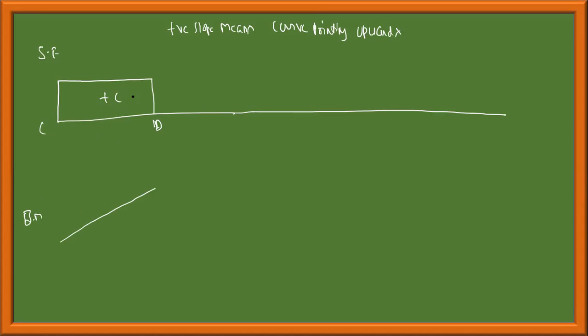Shear force is constant, bending moment will be linear. This is bending moment linear since this is a positive slope. So a positive slope means the curve has to move upwards from point C to D. This is linear. Next, shear force is linear, like this, C to D. Okay, and bending moment. When you see what I have told you, you should always remember this.